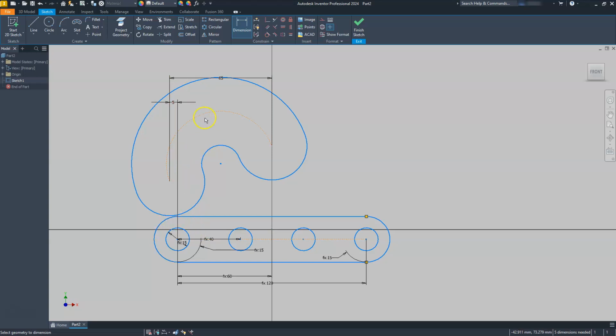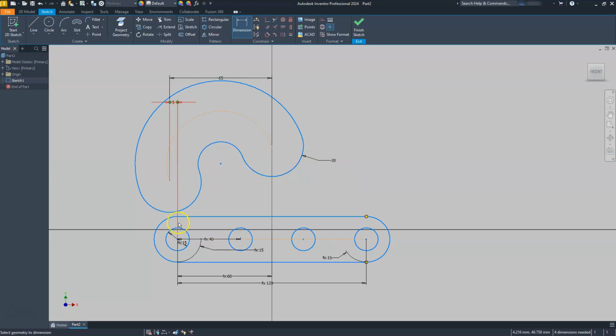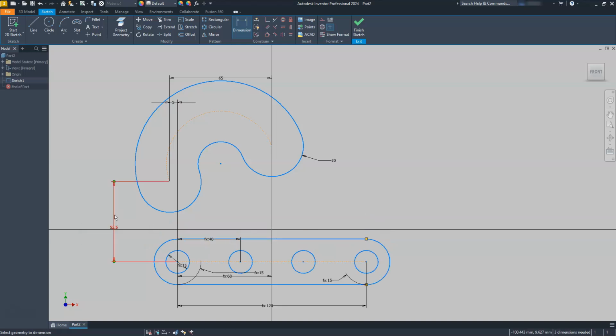Now, don't get me wrong, it's going to start looking a little balloony, but we can finalize some of this stuff. If I go ahead and put this radius dimension on here and set it equal to 20, that should start shrinking some of this down a little bit. Let's put a dimension from that center to this one. This one has a distance of 52.5. And then let's put one more dimension from here to here. That dimension is 37.5.